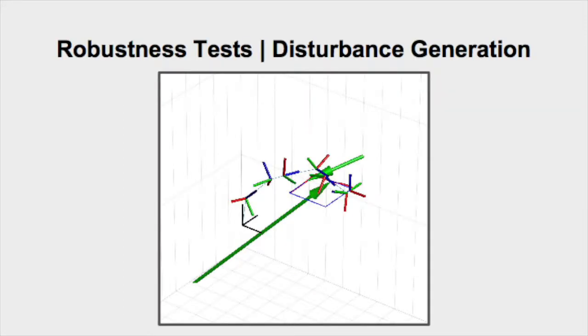Finally, we also wanted to explore the robustness of our controller. To do this, we modeled disturbances as forces applied to the end effector of the robot, which approximated someone pushing the robot in some direction off its trajectory. We generated the forces with some predetermined probability at each time step, and normally distributed their components with a standard deviation of about 1 Newton.